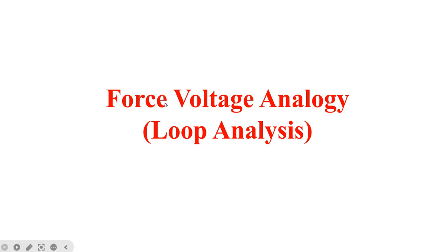Hello everyone. In this lecture, we'll understand and derive the analogous elements of the force voltage analogy, that is also called loop analysis. It is based on the loop analysis. Now in this method, the force in the mechanical system is analogous to the voltage in the electrical system. Here we'll derive the other analogous terms for this force voltage analogy.